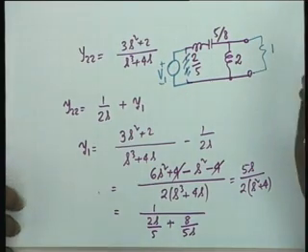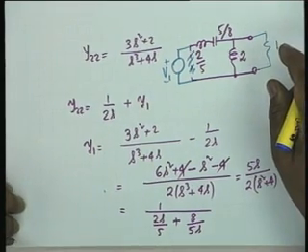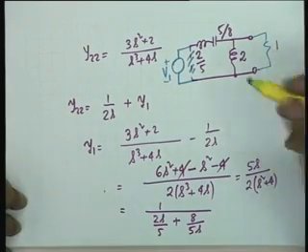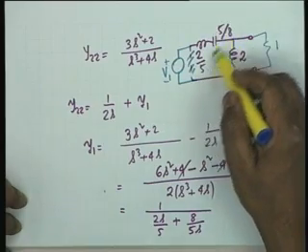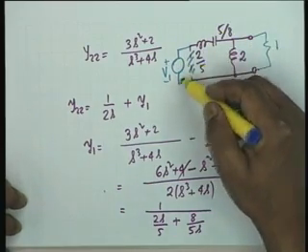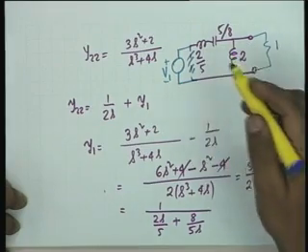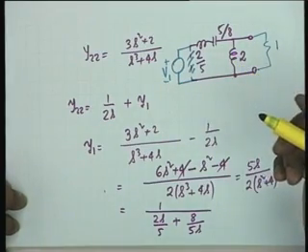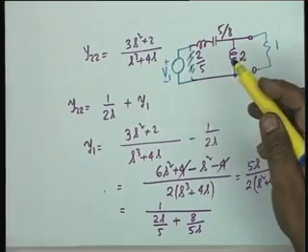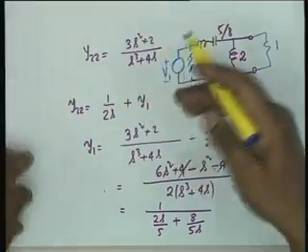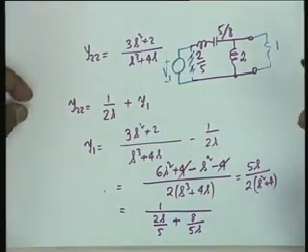What kind of a filter is this? Band pass, that is correct. It is also obvious that when these two resonate, the total voltage appears across this, correct. This becomes a short circuit only at the resonance frequency. At 0 it is 0, at infinity it is 0, in between it has a maximum and therefore it is a band pass filter.